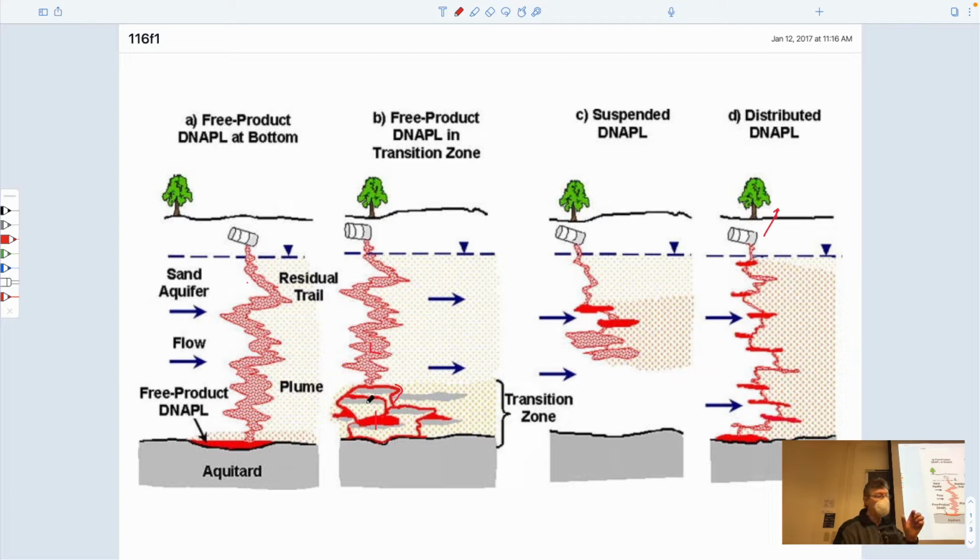As the capillaries get larger, then the bubbles can go in, and they can go straight across these layers. And of course, that would be the case for this so-called aquitard. It's not really an aquitard. We'd probably be better off calling it a capillary barrier, a barrier that resists by capillary forces to stop things coming through. And so that's kind of the place where we are.